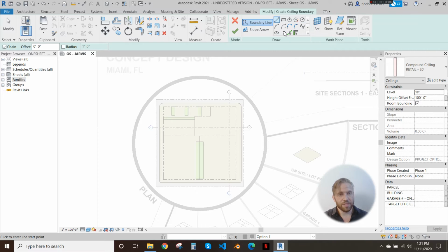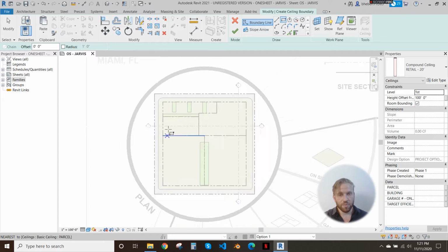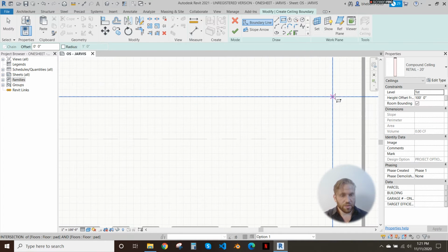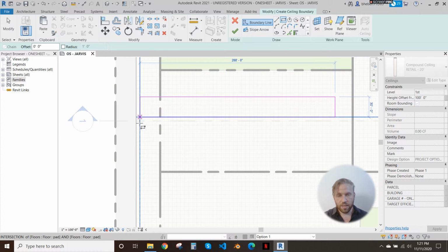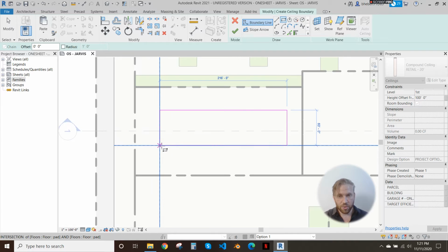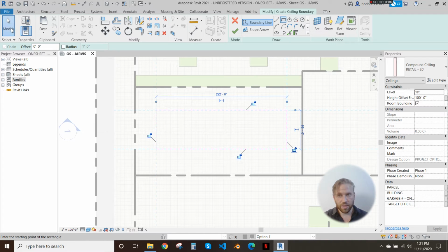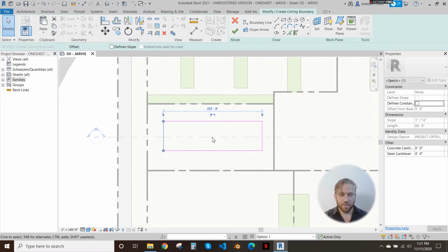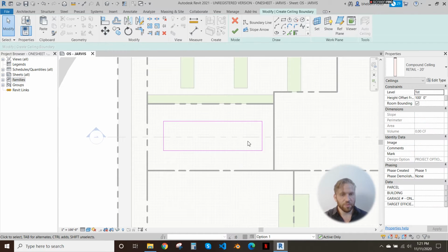This pops up again back to your boundary tools, your line tools. I'm just going to select this rectangle tool here. I'm going to zoom in, and because of the grid pattern I have on this curb building pad floor layer, it kind of snaps to the hatch that's placed on there. And I'm just going to create that, and you can change the dimension of this pretty easily. I encourage you to play around with how to create these lines, but for now I'm just going to show you how to do the real basic stuff.